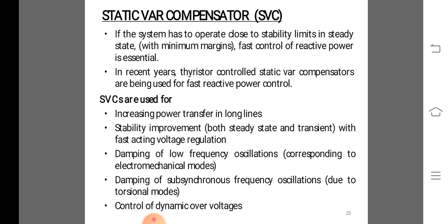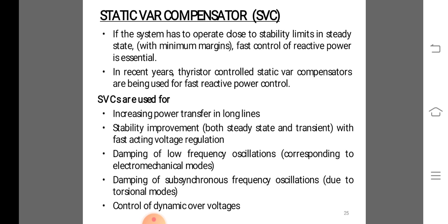The thyristor controlled reactor, that means TCR, is operated on the low voltage bus. In another form of the compensator, the reactor is connected to the secondary of a transformer. The primary winding is star connected with neutral grounded, suitable to the thyristor network.